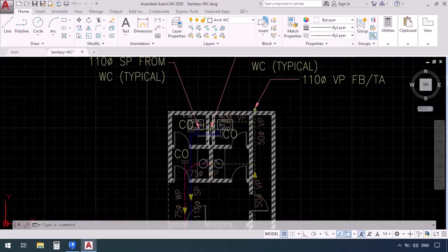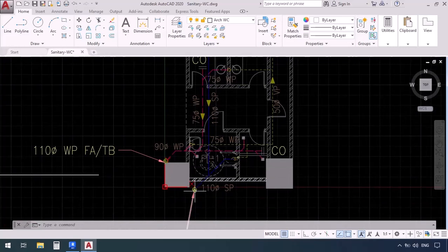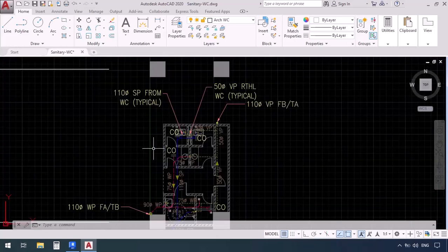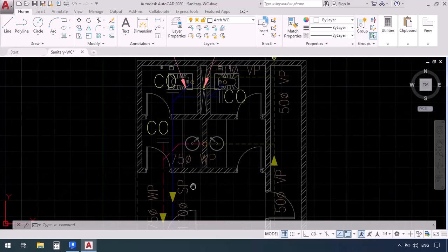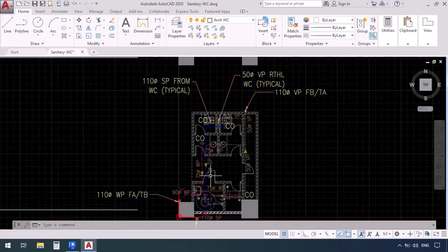Now we're going to start with modeling the soil pipes or the heavy waste, and we will be connecting these eastern toilets and this western toilet to the riser. Now, another thing is that for the size of the pipes, here it says 110 for a pipe of the polypropylene segment, but now we're just going to draw this pipe from the PVC segment. For a PVC pipe, we use the size 100 instead of 110. So we're going to load all of this in the project so that we start to model its pipes.